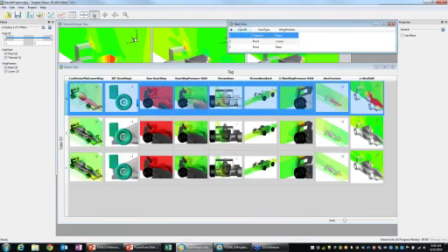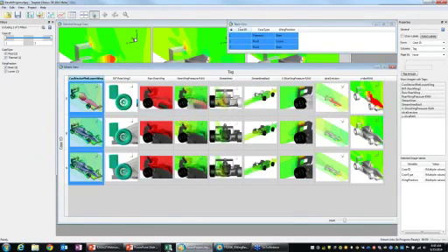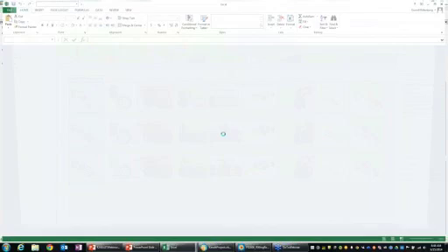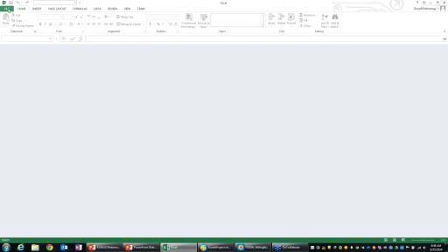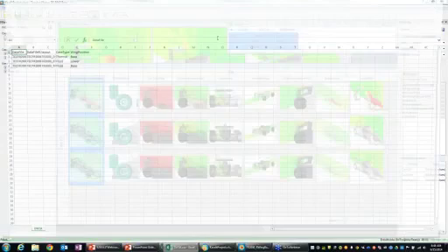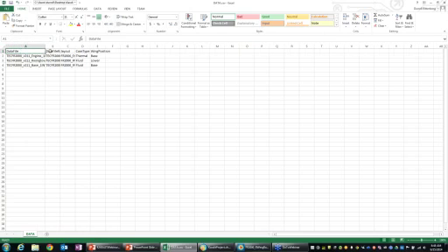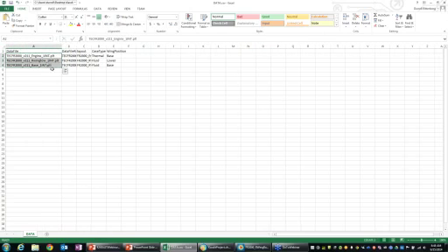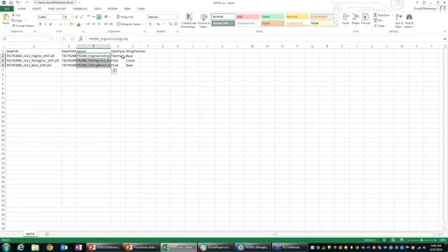And you can see that I have the 3 cases, and how I generated those cases was actually very simple. And I'll open up the file so you can see it. So I generated a very quick index file where I put in the information about the individual solutions. I put in information that I happen to have a layout. And then I categorized them as whether or not it was primarily fluid dynamics or thermal, and determined whether it was the base case or whether or not we were looking at the modified geometry. And this is all I needed to generate a project in Tecplot Chorus.